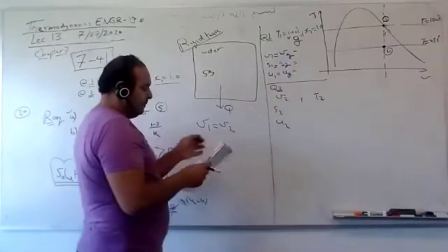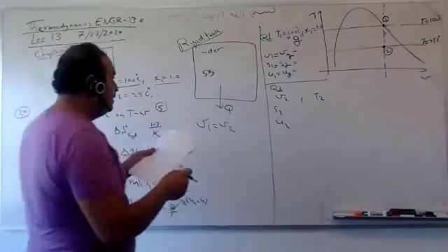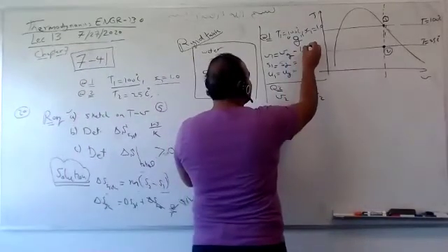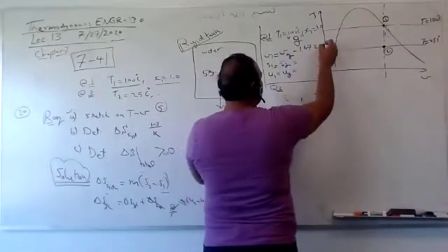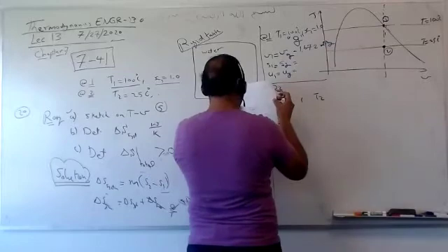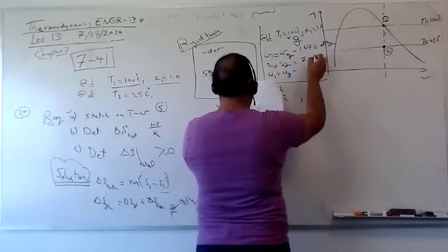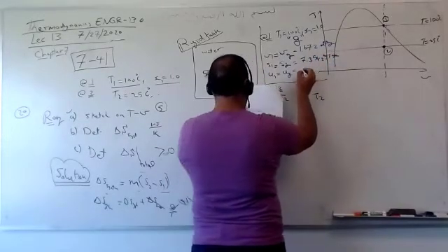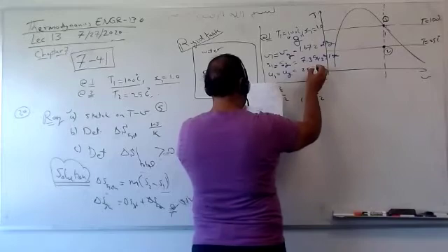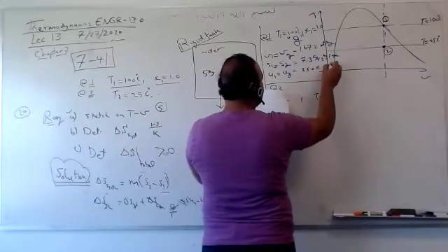These are specifics. If you open table A4, you will obtain these values: 1.67. Actually, I wrote this number many times. Meter cube per kilogram. Don't forget the units, please. 7.3542 kilojoule per kilogram Kelvin. 2506 kilojoule per kilogram.